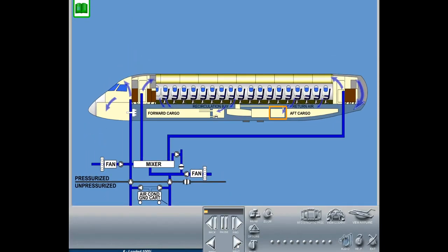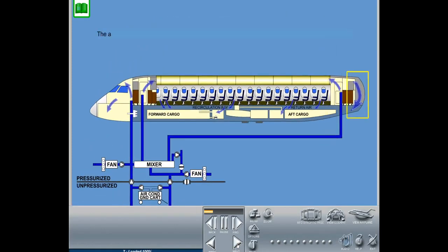The center E-bay ventilation system has 3 fans, which provide forced cooling air for the center E-bay electronics, the left and right integrated control centers, and SPDA-2. The fans draw air from the rear cabin return and expel it towards the underfloor recirculation bay. Flow sensors are used for fan flow health monitoring. The aft bay air flows from the passenger cabin and is expelled towards the underfloor recirculation bay.